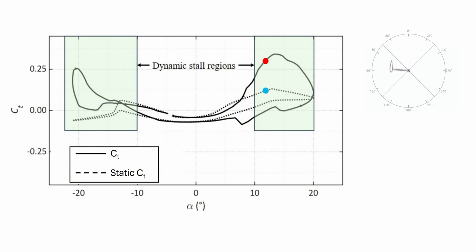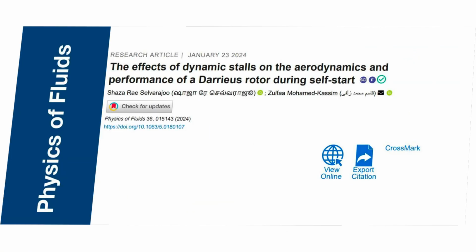One tricky thing about computing this static thrust coefficient is that the instantaneous blade Reynolds numbers are changing all the time, which means that the polar data you need to use will change at every single time step. I've validated the algorithm many times over, and the results that came out of the algorithm were eventually published in Physics of Fluids, so it's pretty legit.